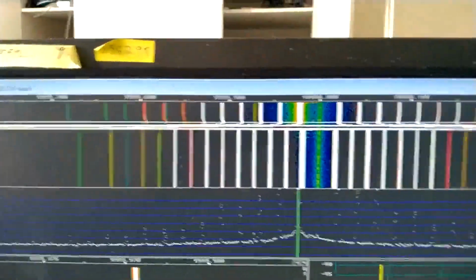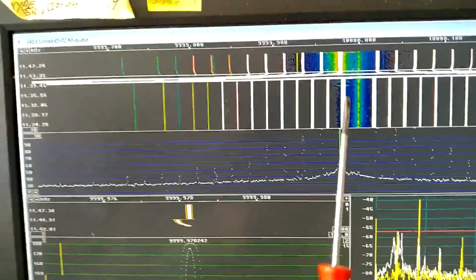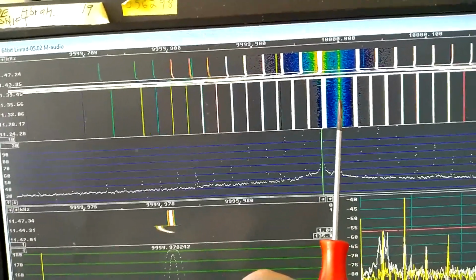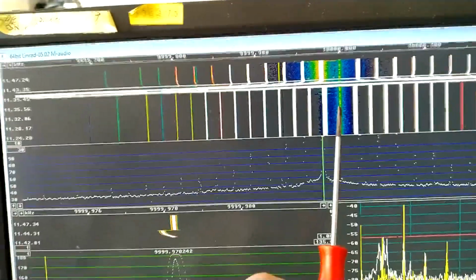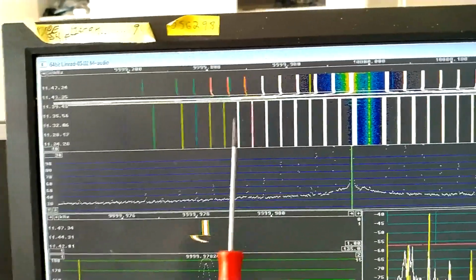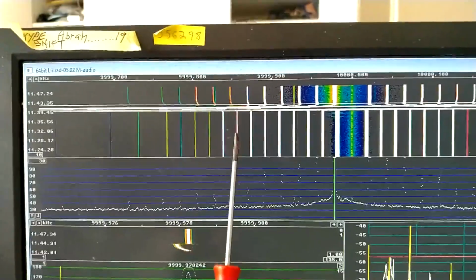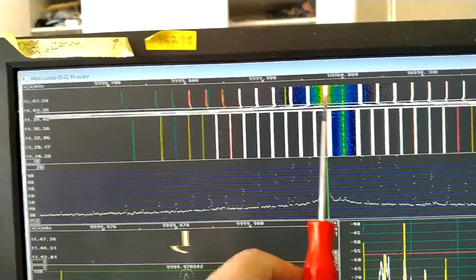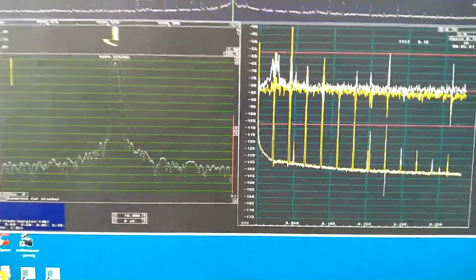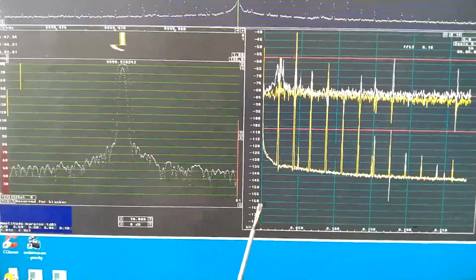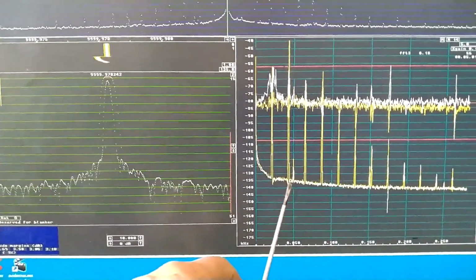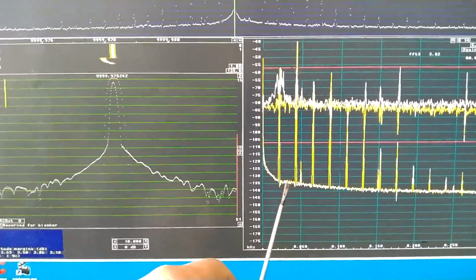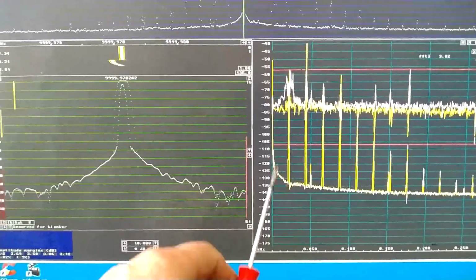and as you can see here, it is much more noisy than the situation before with the Wenzel oscillator plus minus 151 dBc of white noise. So you can see here the noise close to the carrier is pretty strong. And it means up to about 50 Hertz there is a strong noise both in amplitude and phase.